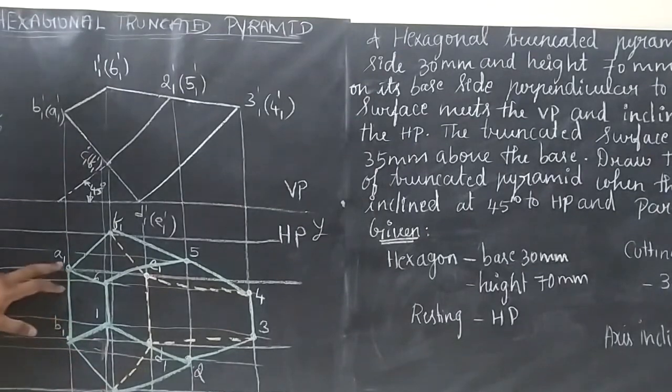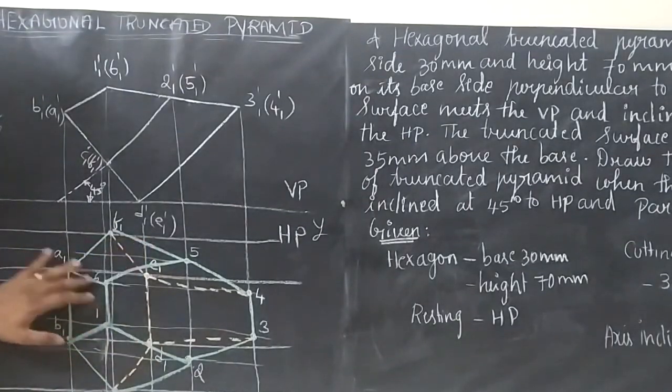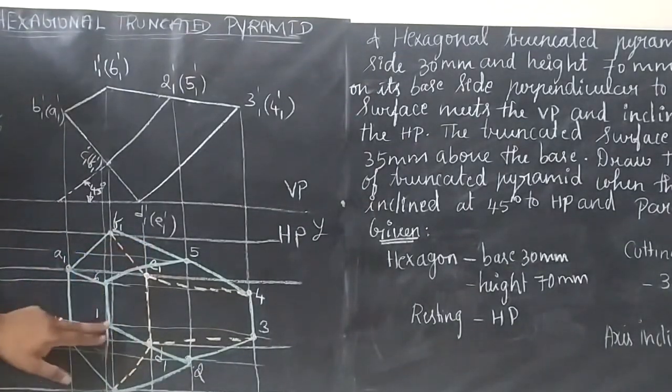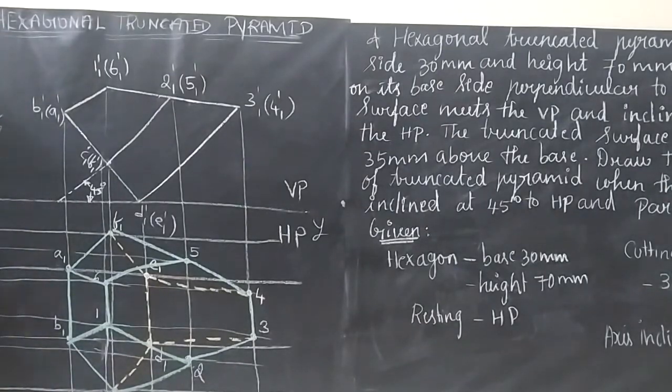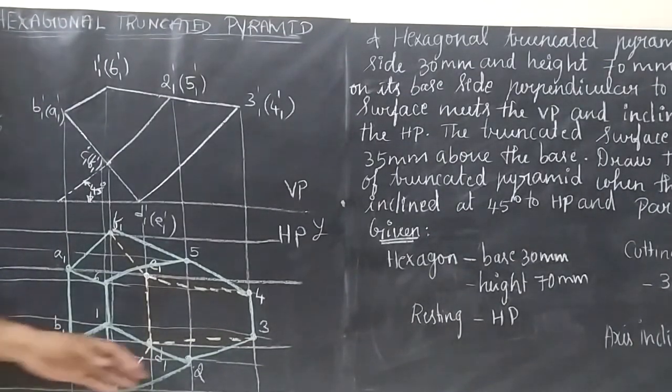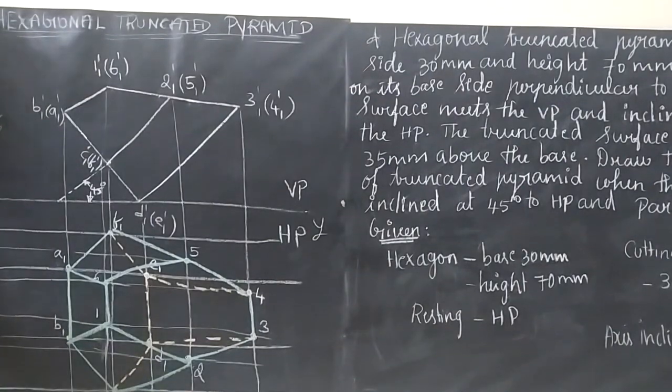And next thing is, see here, here we will be having one face. So A to 6 and B to 1. So now if you join all these things, you will be getting the complete solid. Give preference for hidden lines. Dimensions, as I already mentioned, you need to dimension these things and all. The heading is projection of hexagonal truncated pyramid. Height of text for the heading should be 10 mm, and at the lowermost bottom you have to write all dimensions are scale